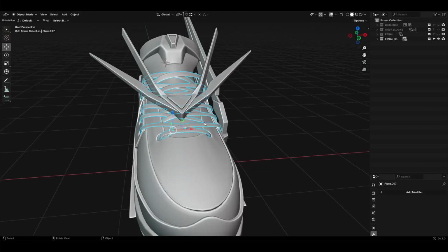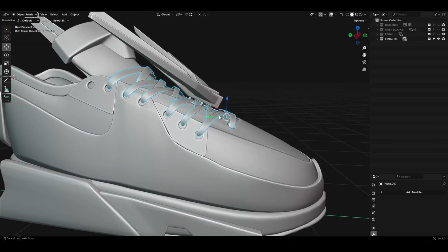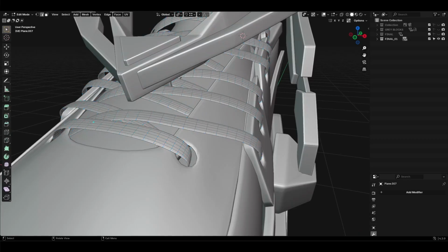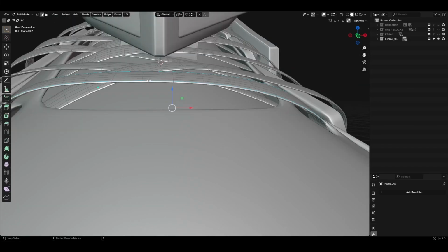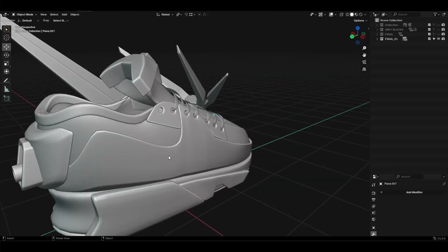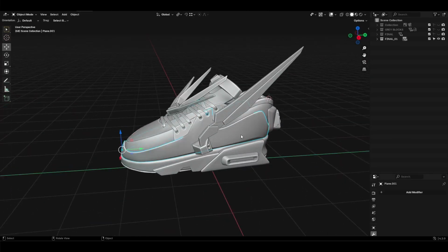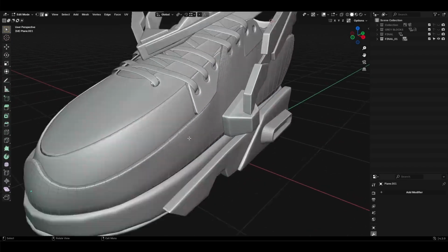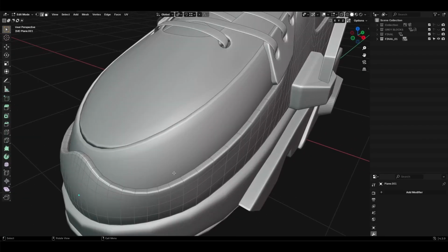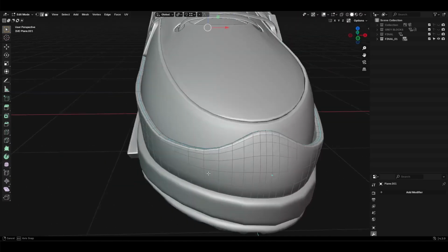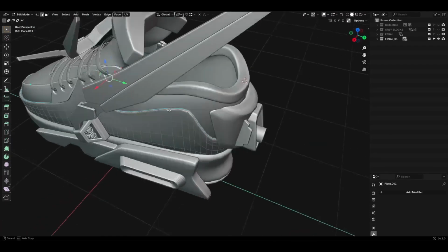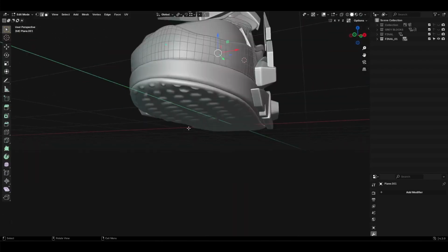Okay, so what we're going to do is just remain this and we're going to individually UV this one, but don't worry, it will be easy to UV because we have created a clean edge flow. So that's the advantage of creating clean or localized edge flow, because if you're going to UV, let's say you select the edges right here, it will automatically loop around the object seamlessly.